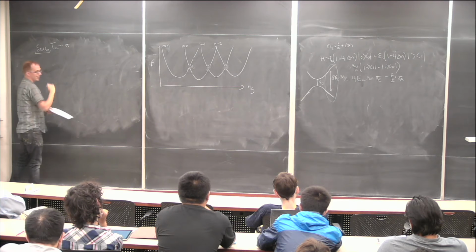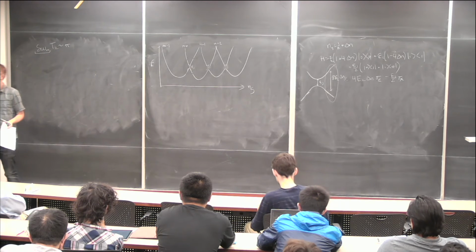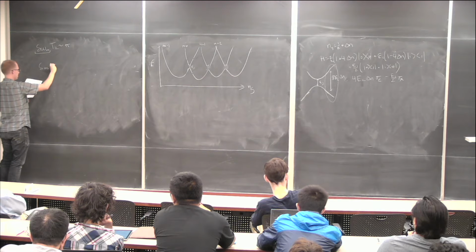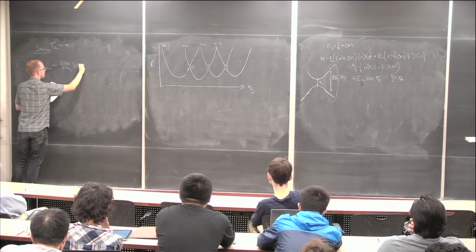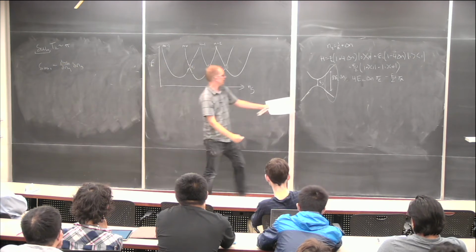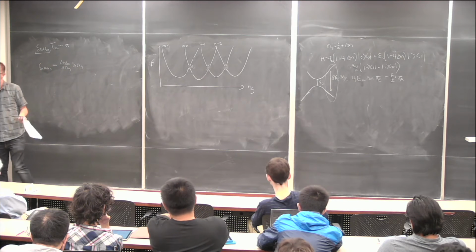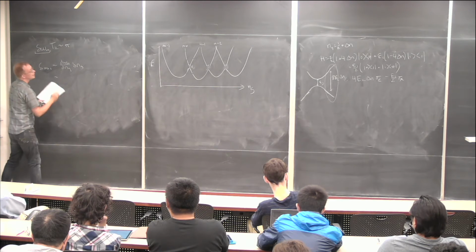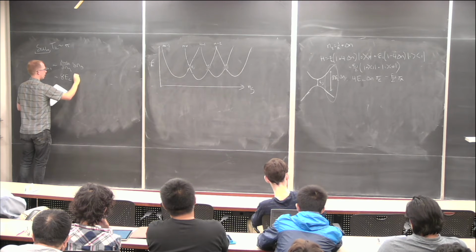And we can calculate that because we know omega 01 as a function of some variable, in this case Ng, our gate voltage. And so we know that delta omega 01 is approximately d omega 01 dNg times our uncertainty in Ng. In this case, we are to first order sensitive in Ng, which is first order sensitive in delta n. And so to the extent that something bad is coming along and twiddling delta n, we know that's going to cause a dephasing that is approximately 8 EC times delta Ng, our uncertainty in Ng. Okay?